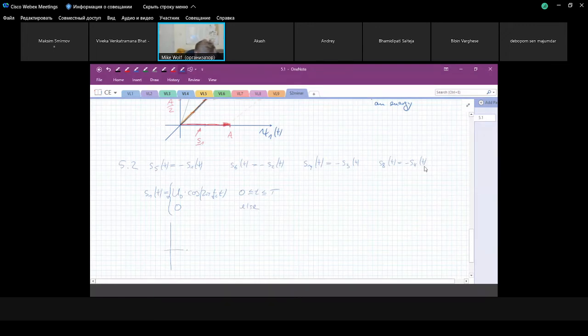And fc, yeah, this is the center frequency, and here we assume, in this example, as it's written, there is an integer number of cycles within the symbol interval. So it's written in the task that fc is just k times 1 by T. So there is an integer number of cycles within this symbol interval.